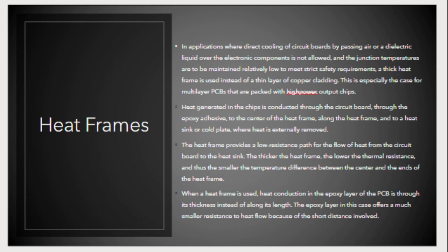When a heat frame is used, heat conduction in the epoxy layer of the PCB is through its thickness instead of along its length. The epoxy layer in this case offers a much smaller resistance to heat flow because of the short distance involved.